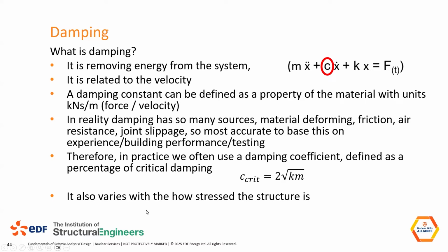Damping also varies with how stressed the structure is. If the structure is behaving elastically, you'll get quite low damping. If the structure is deforming, creaking, groaning, with some plastic behavior, that means you can use a higher level of damping, because that is removing more energy as it's deforming. So you might get different damping levels for the same structure depending on how hard it's working.